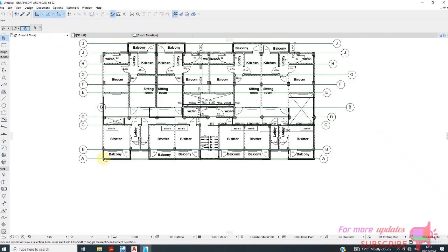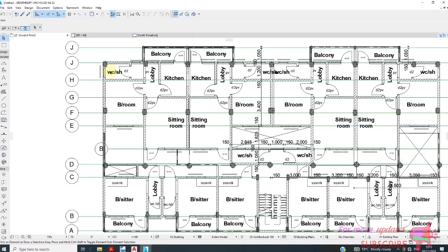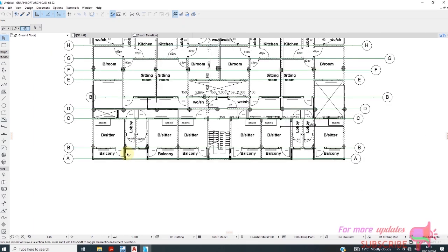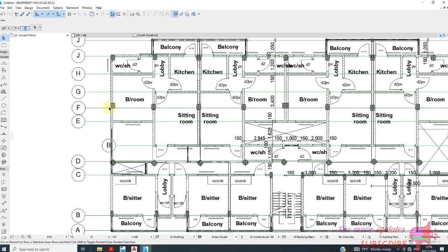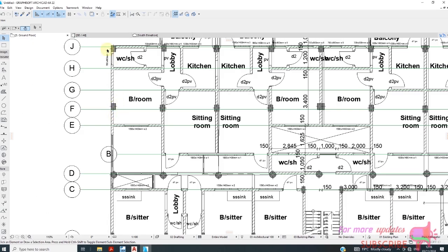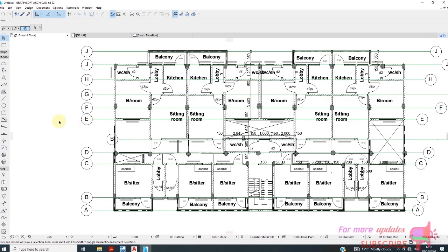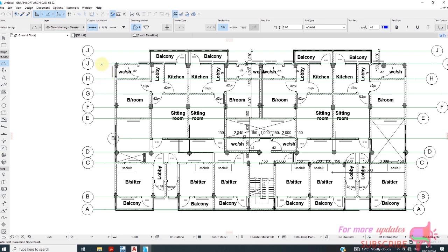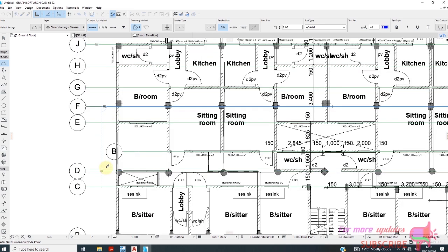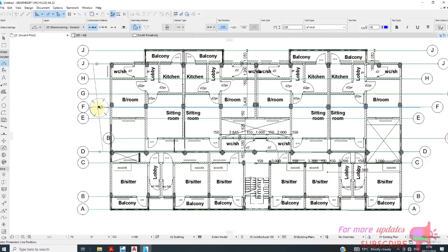Now you draw grid lines in this direction. But first, I need to dimension. I need to know the distance from this to this. So I need to know the exact. You can consult with the architect, but as an engineer, you can also decide using structural experience to know where these columns should be. I think they should be somewhere at the midpoint because there is no other column there, and you can see that span there.